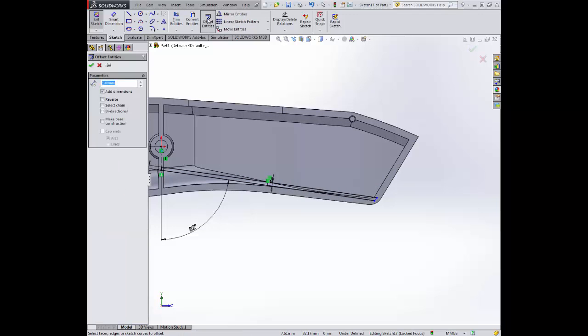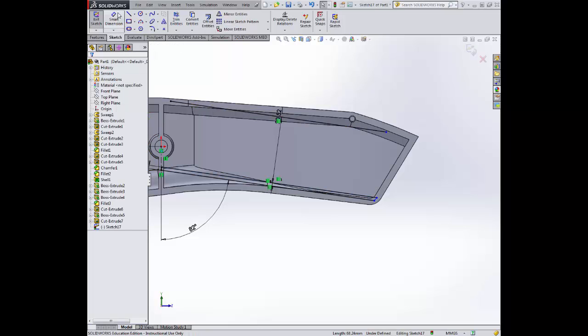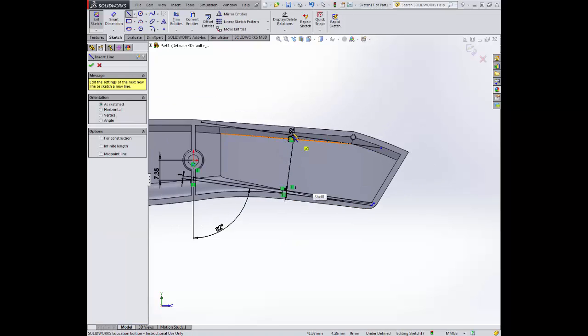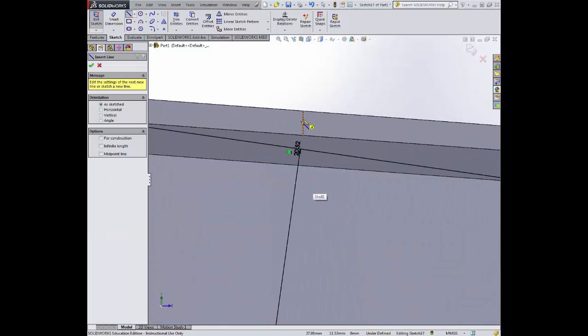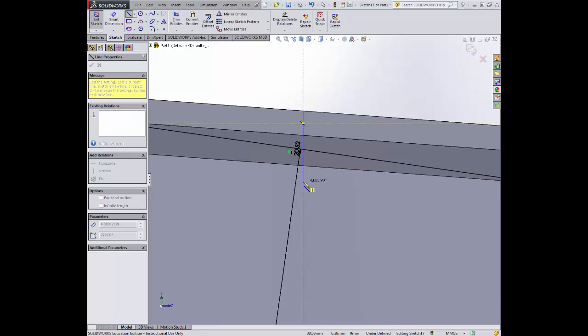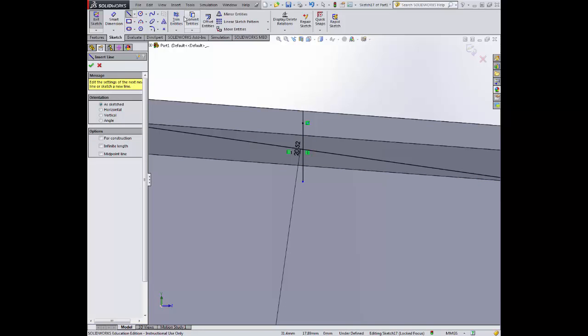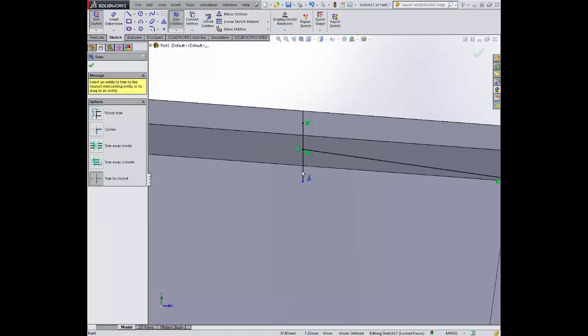Okay, we're now going to do the top face. So use the top line, reverse it, and then this dimension here, 20.52. That has to be precise, otherwise you'll get collisions and issues. So from this line here where we've got the cut, we're going to come straight down. And we're going to trim out the lines we don't want while we're here.